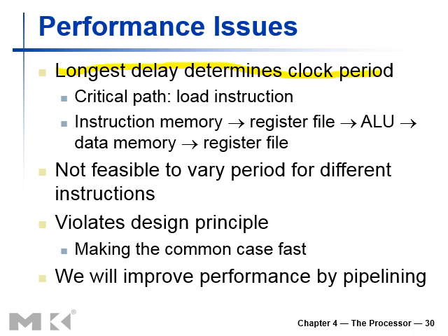So we have to set the clock cycle time equal to that, because if we set the clock cycle time lower than that, some of the instructions could be executed, but not all the instructions. So we have to select the clock cycle time in such a way that all of the instructions are executed. Which instruction will be affected mostly? The jump instruction, because the jump instruction only requires the first process. So the rest of the time is just wasted in that particular scenario.